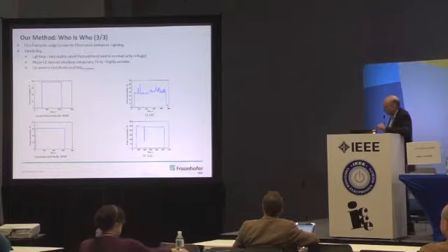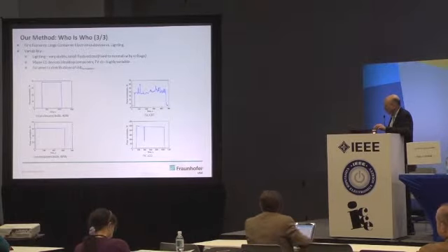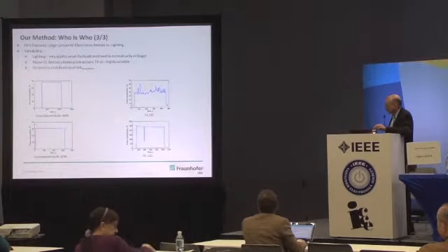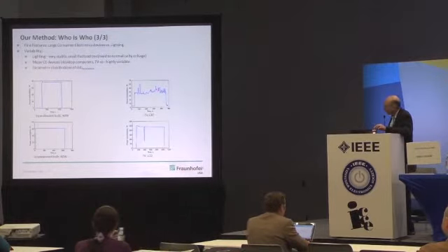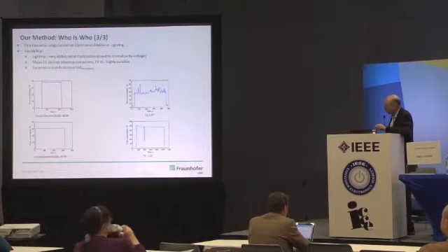Now, if you recall the idealized picture on one of the first slides, I believe it is slide number 4, for the television, coffee maker and refrigerator, the power draw of the television was considered to be constant there. In reality, it is not constant. For a CRT, we can get a picture like that. Why is it so noisy? Because there are frequent changes of brightness, and also we need to remember about the audio.